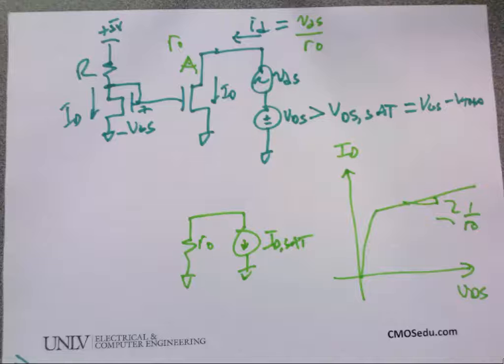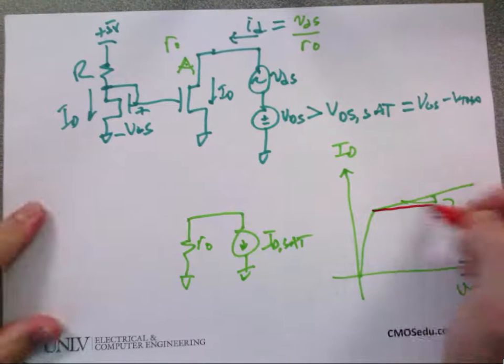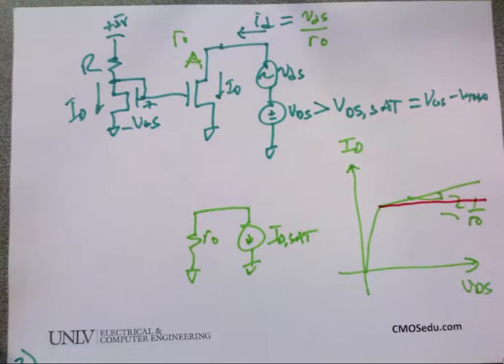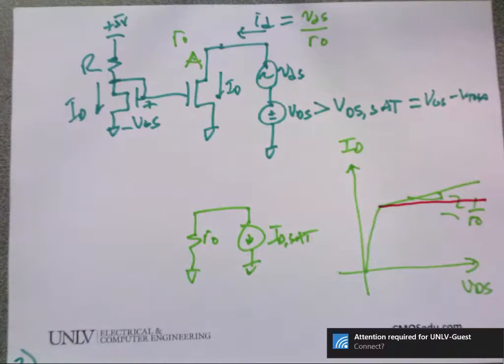All right, so what we're going to do is we're going to try to increase the output resistance. Why is that? If we have a flat output resistance, what's that? You get less of a slope. Yeah, but why is that important? What if we have a slope like that, no output? What do we model this as? A current source. It's a more ideal current source. Does everybody see that? Okay, so I get a more ideal current source. I want a more ideal one when I'm doing designs because then I have, we'll see later, higher gain, more ideal behavior, etc. That's 3.